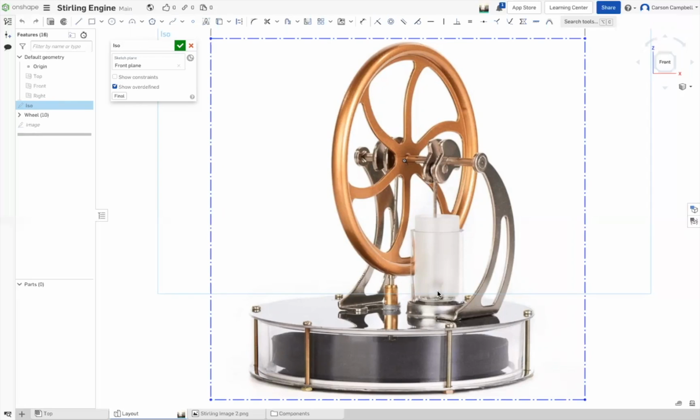Okay. If we did these independently and you made a change, if you increase the height of that bracket, you get to go through and change all the parts. Yeah. If you did these all inside of a part studio, we could put the parameters in there so that once you change the height of those brackets, everything would update. Your choice is, do you care about that or do you not care about that? I mean, I don't want to go back and have to fix everything.